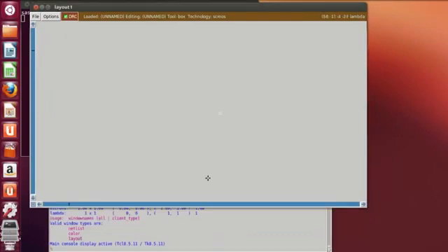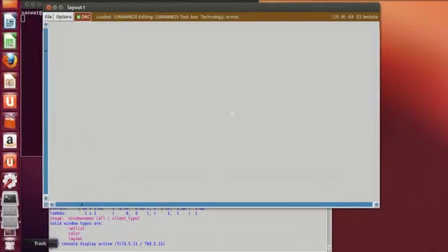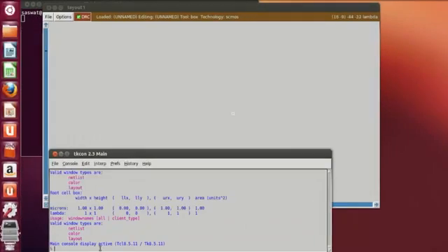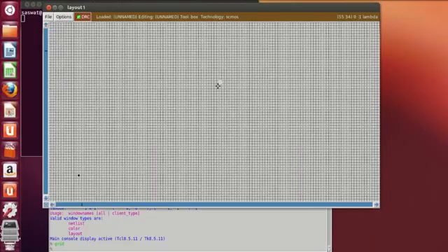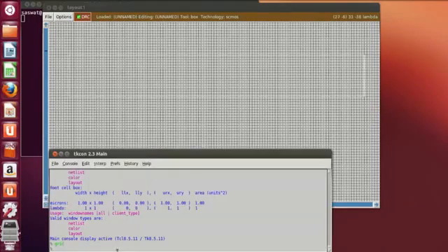So this is the layout window. We will draw the layout by using the commands. So at first type grid in order to grid in, and after this you have to create the n-well. So type paint nwell.